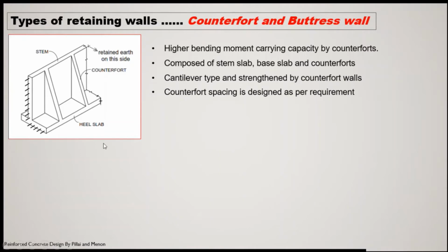Counterfort spacing. Now, the spacing between the counterforts will be decided as per the requirement. That means the major benefit is on this particular slab. Now, when you are putting counterforts, what you are doing is decreasing the span of the slab. So that means you will be designing the slab in the form of some panels.